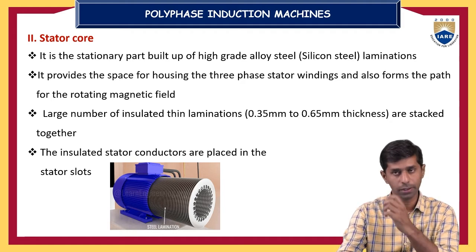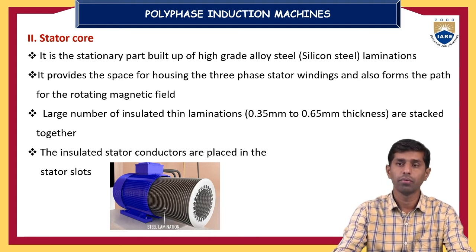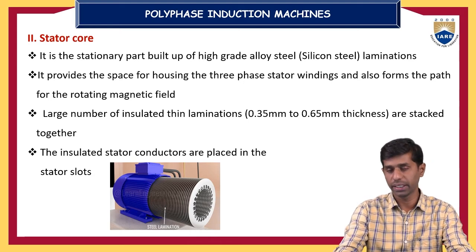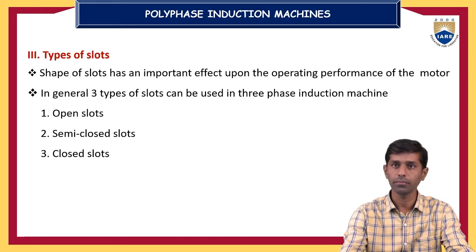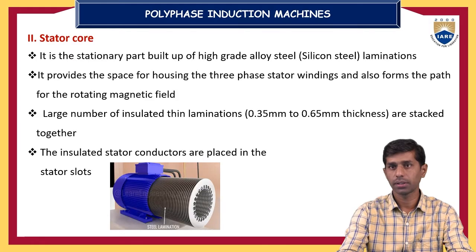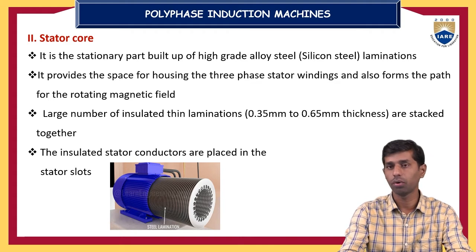So laminations are required to reduce the eddy current losses in the stator core. These laminations are stamped under hydraulic pressure, and they form a stator core.